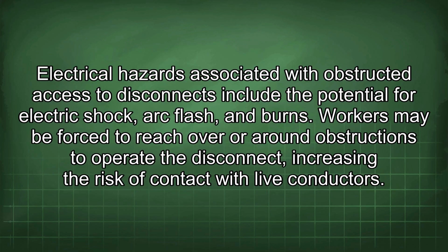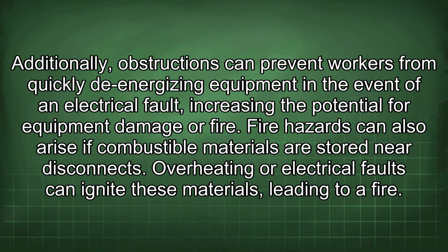Electrical hazards associated with obstructed access to disconnects include the potential for electric shock, arc flash, and burns. Workers may be forced to reach over or around obstructions to operate the disconnect, increasing the risk of contact with live conductors. Additionally, obstructions can prevent workers from quickly de-energizing equipment in the event of an electrical fault, increasing the potential for equipment damage or fire.